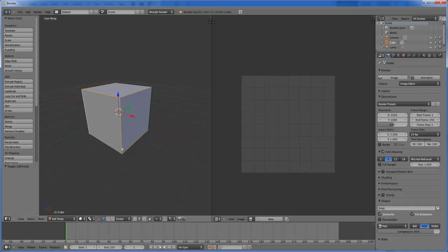So having selected these edges, if you press Ctrl E, that brings you into the edge function, and you want to mark the seam. So click this, and if you select the other one, you can see that all the seams that have been selected have been marked red, and the computer algorithm that will unwrap this will use this seam to unwrap this box nicely onto this surface.